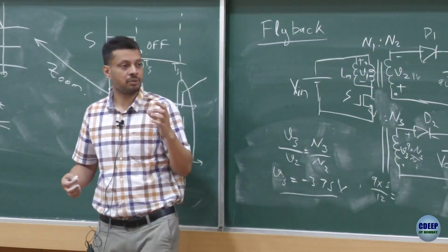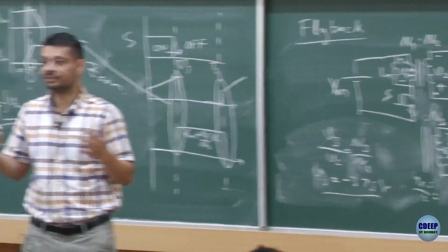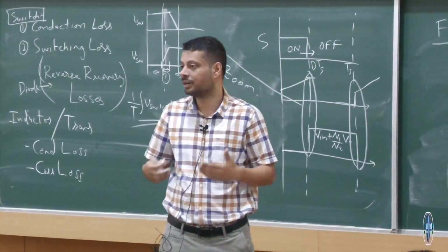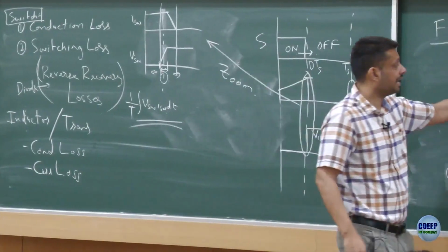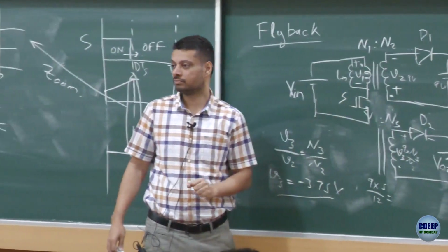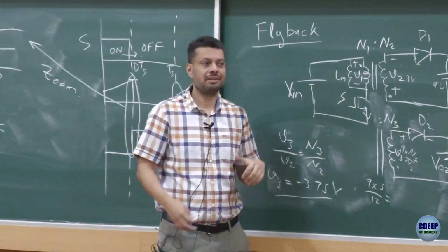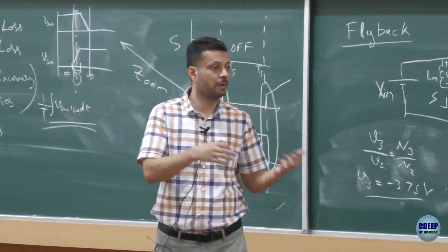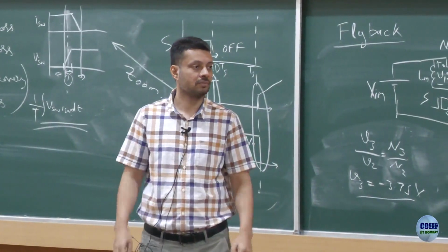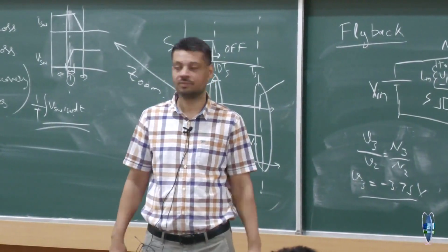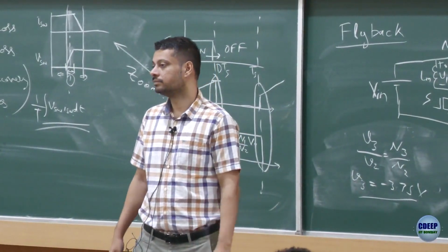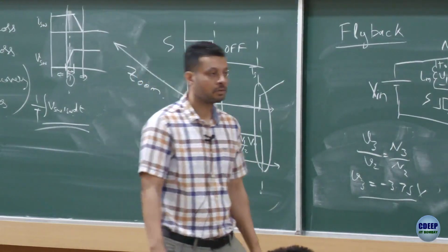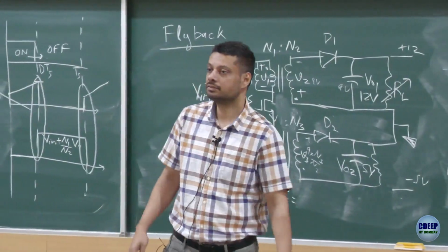In reality, whenever you take transformers, you would want to have a larger Lm value, which is closer to the ideal transformer. In reality, never ideal, but closer to the ideal. So if Lm is large, the energy transfer would be small, right. So naturally this circuit may not be suitable to transfer a large amount of power from input to output. That's what he is saying. Is that okay? Any question?